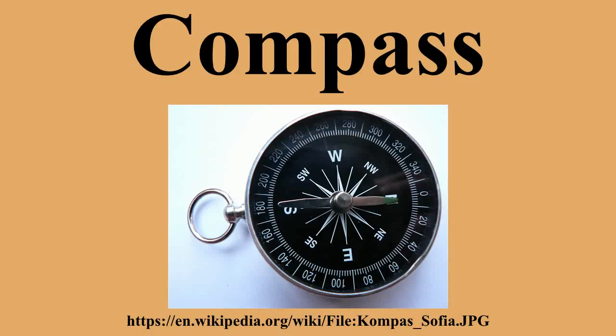Solid-state compasses. Small compasses found in clocks, mobile phones, and other electronic devices are solid-state compasses, usually built out of 2 or 3 magnetic field sensors that provide data for a microprocessor. The correct heading relative to the compass is calculated using trigonometry.